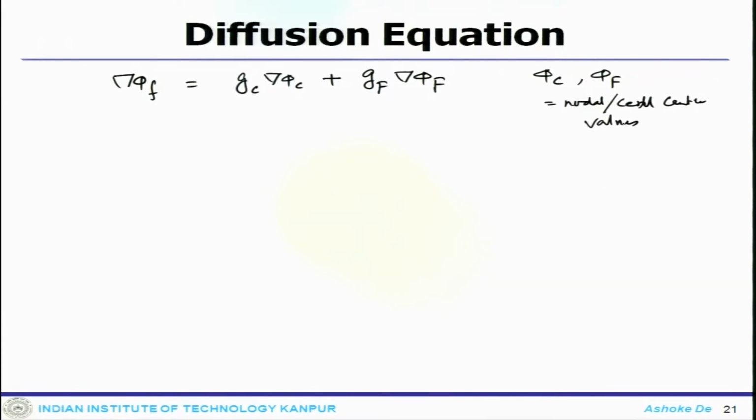So, you use the information of the cell center values to get this particular information. Once we use the cell center values, we can linearize the system using that information. Now, if you look at the whole summation term over the cell, it is essentially J f for the diffusion term S f.